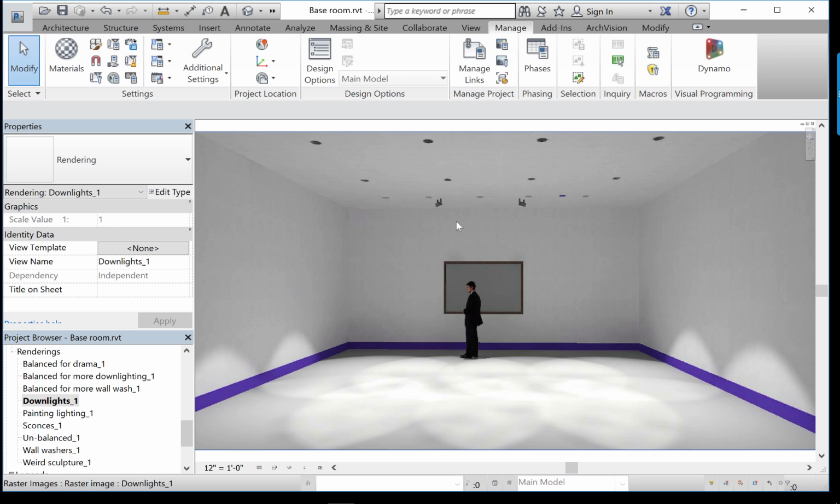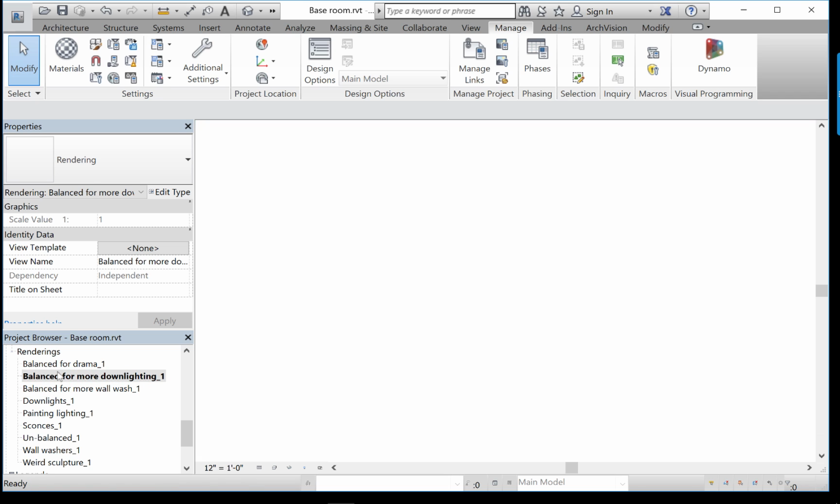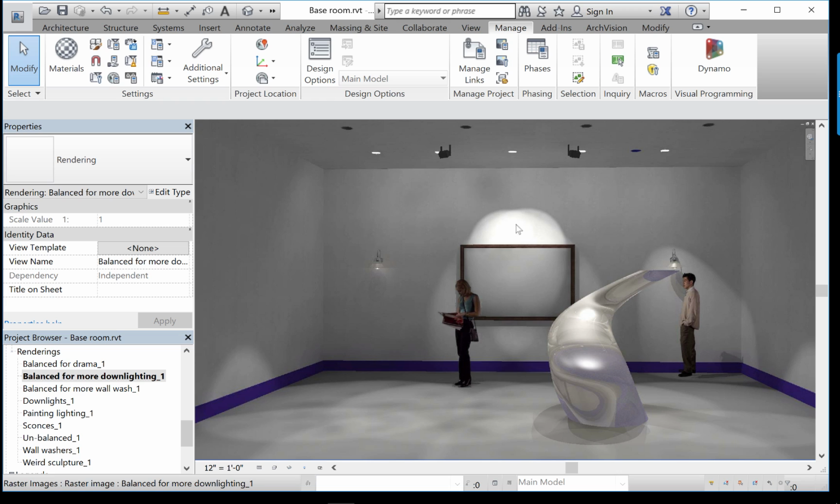You can take a Revit model and really improve the lighting in a big way just by using a number of different subtle techniques, including changing the light source direction, the light source definition, the angle of the beam spreads on the light source, using glowing materials in different ways, and finally balancing the whole kit and caboodle so that you come up with a presentation that is dramatic.